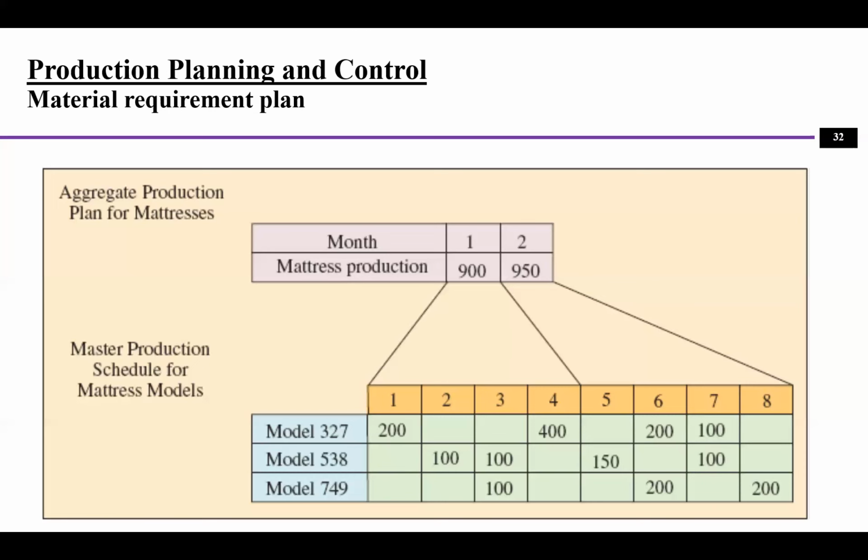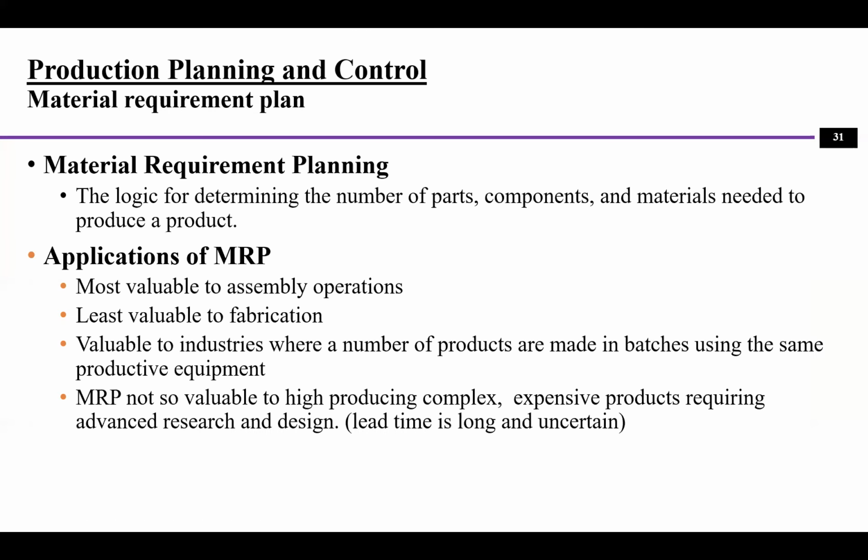All right, and so the typical applications of MRP will be mostly valuable to assembly operations, because assembly operations usually involve a lot of parts to be there at the same time. But it's least valuable to fabrication, because you do not have a lot of parts and they are also outsourced from other suppliers.